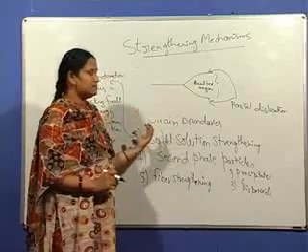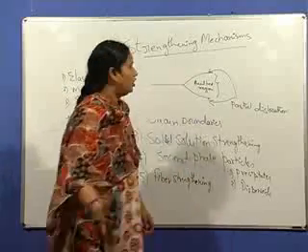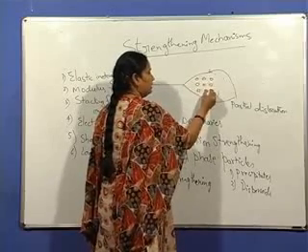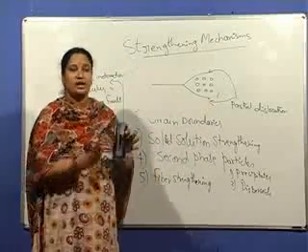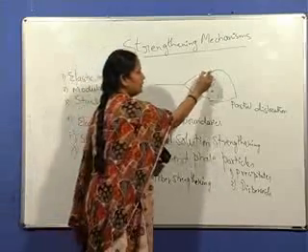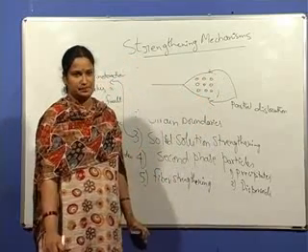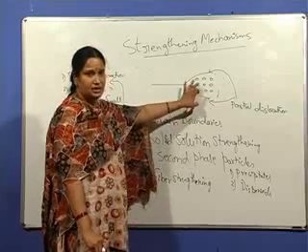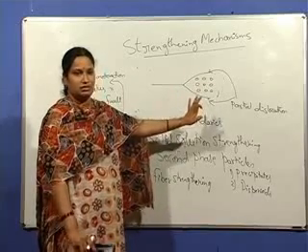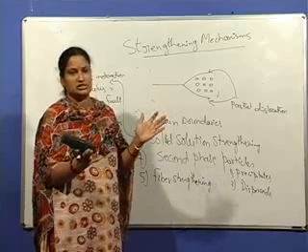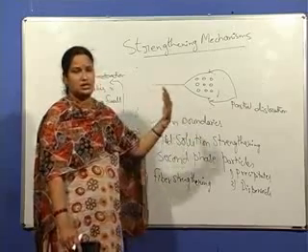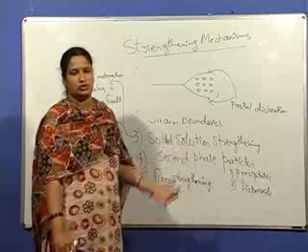So the solute atoms segregate into the faulted region of the stacking fault and lower the energy. If the energy is lower, the faulted region is wider, and there is more separation between the partial dislocations. As the concentration of solute atoms in the faulted region increases, the energy will be lower. The lower the energy, the more the separation between the partial dislocations and the more the faulted region. So there will be more constrictions for this extended dislocation to move, whereby this also contributes to strengthening.